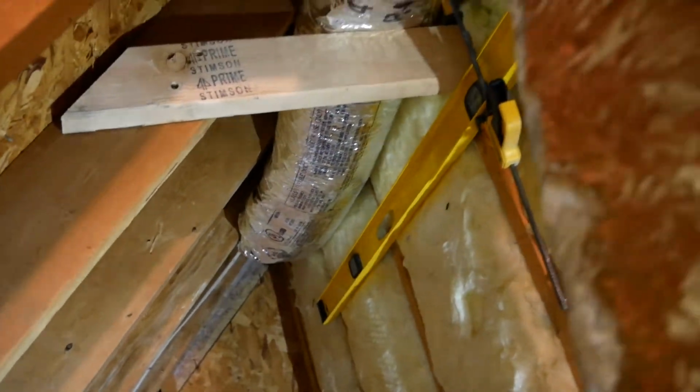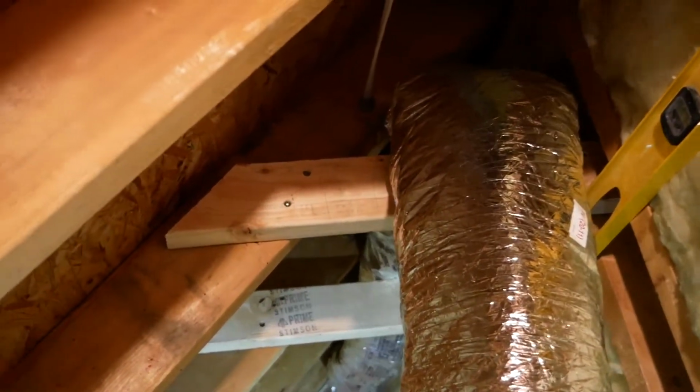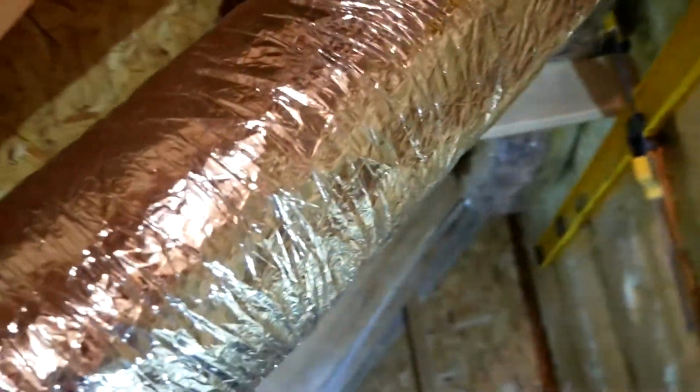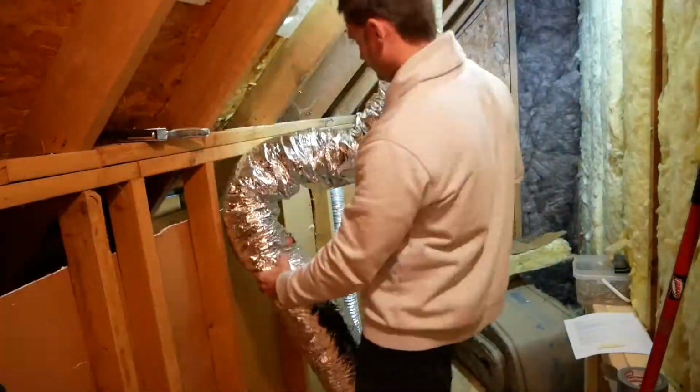And I'm building a little roof area here because I'm going to drywall this in. So there's going to be a bit of a ceiling. So that's running through there. Then all we need to do here is run this along the side of the rafter up in this little bay, and then we will run it down here, and that's where it will exit out the soffit vent.